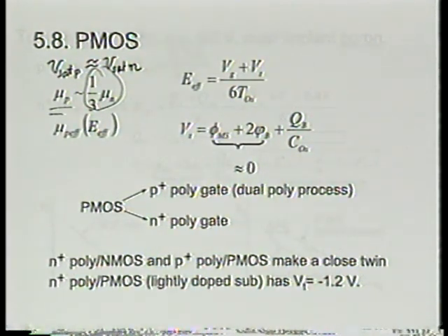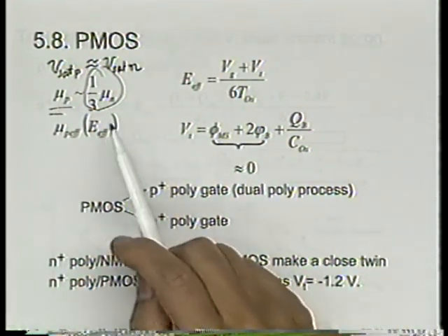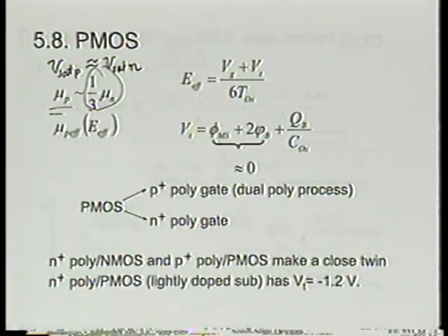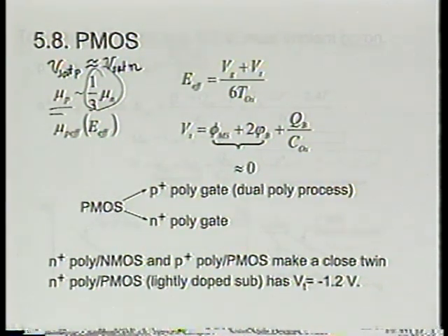Why is it that the N-channel transistor current and P-channel transistor current are not approaching each other? In other words, it seems that mobility continues to play a role, right? So how can you understand that? All right, but that's a fact, okay? That mobility differs by about x3, saturation velocity differs by only about 30%, and the current happens, as a result, to be about a factor of 2 different between the two, okay?